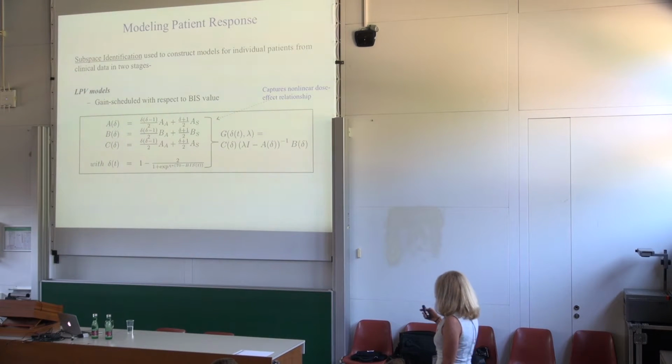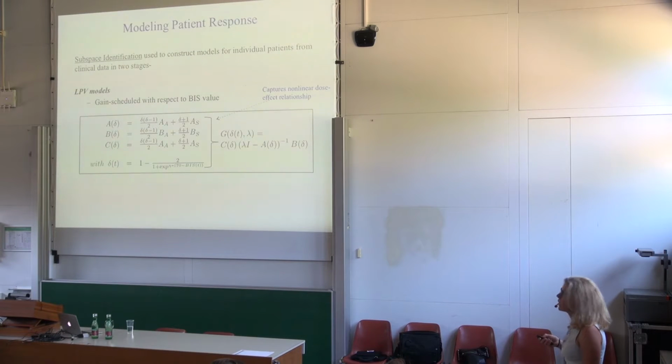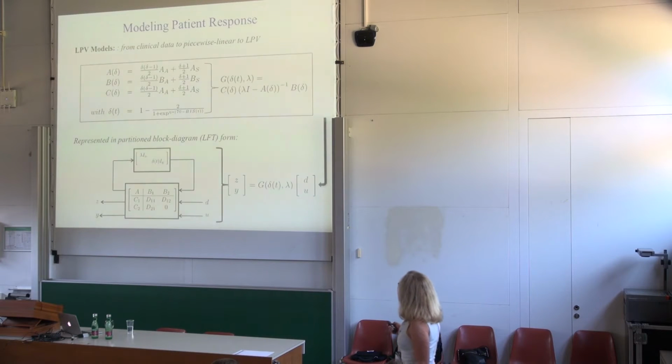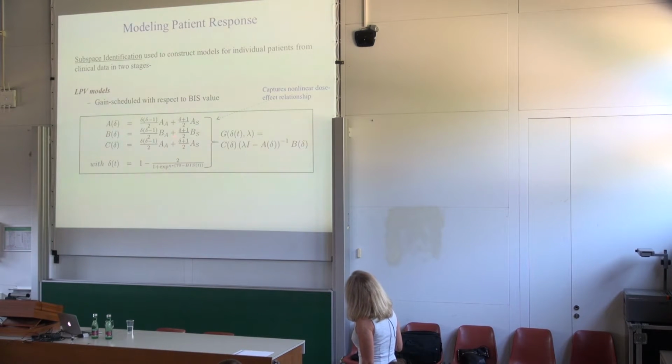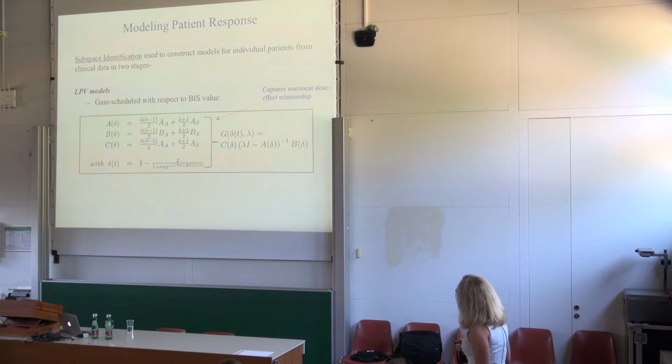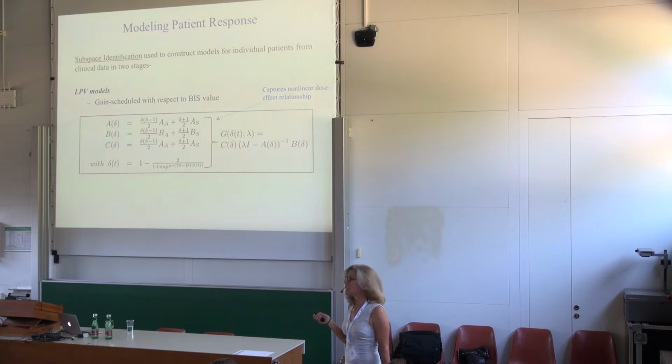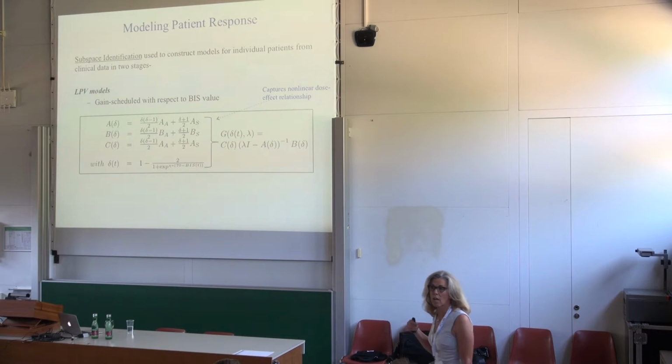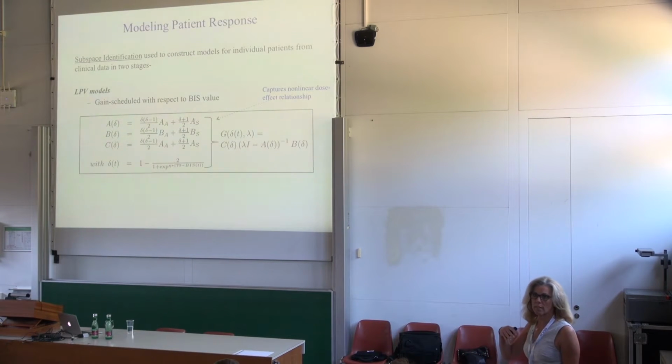So basically what we're doing here is smoothly gain scheduling between our awake and sedated models with respect to a BIS value. So we modeled this switching or smooth transition using this time varying parameter delta, which is essentially capturing this sigmoidal type dose effect relationship, right, for this MIMO model, that we see when we administer drugs and go from, in this case, alert to sedated.